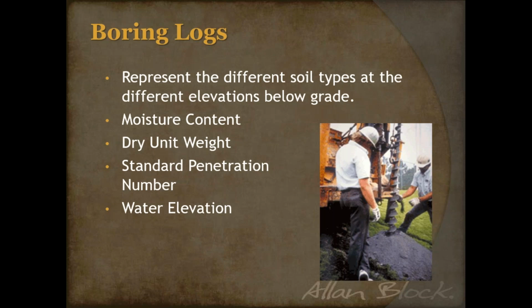is with the penetration numbers, and then we get back into that water elevation again, building again on what Logan emphasized, that if you've got a hole, we can measure the water elevation if there is one in the hole, and find out if we've got a perch table or that's something that might cause problems in the long run. So it's all identifying those potential water sources. But the only way to do that is through exploratory drilling. And here's a kind of a summary of it.